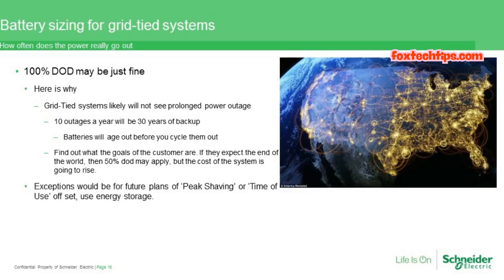When we talk about what the right amount of energy storage is for AC coupling or even grid tie with battery backup, around 440 amp hours is our recommendation for the XW Plus. And for the SW, just simply because in general it's a smaller system that it's going to be attached to, it ends up being a little bit smaller number at 200 amp hours.